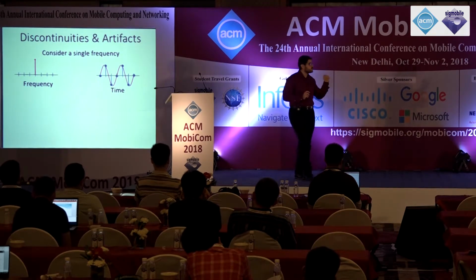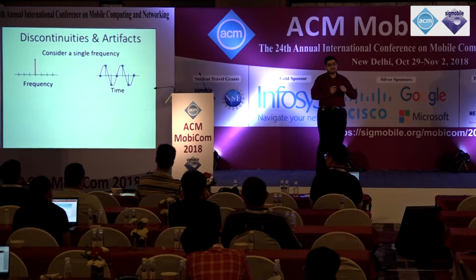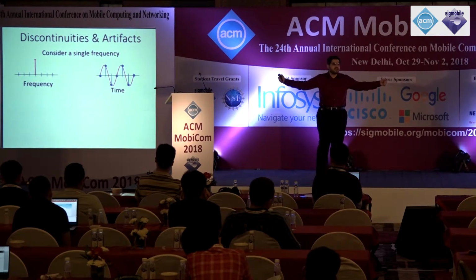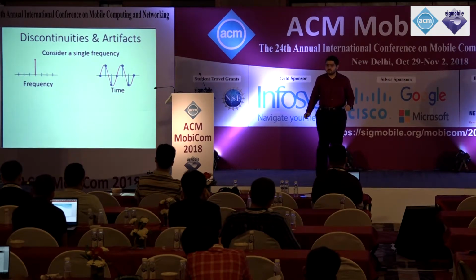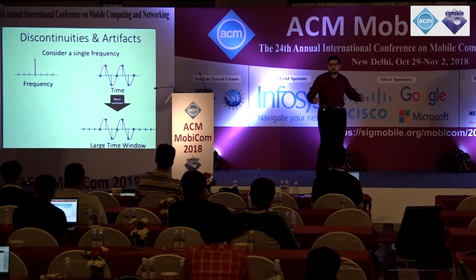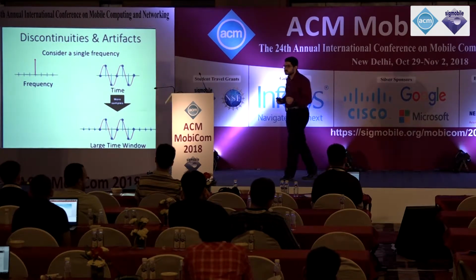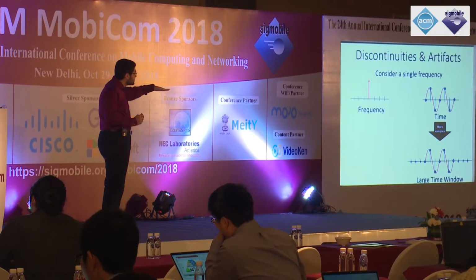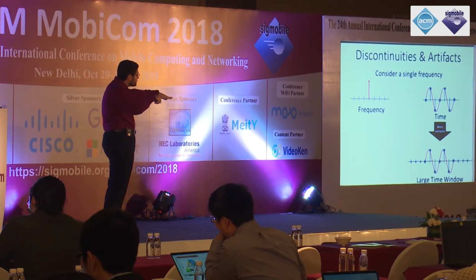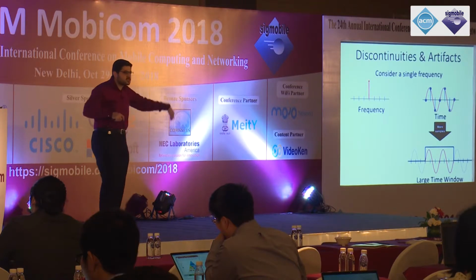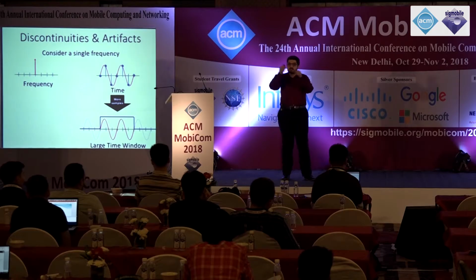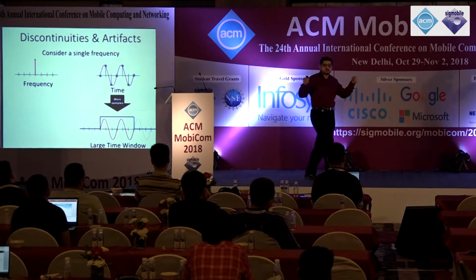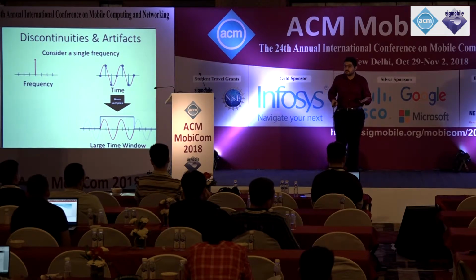Now, what did Ghostbuster do? What it did is it took an FFT over a way longer time window, something like this, way more than what we transmitted. You can think of it as a much longer sine wave that we cropped, as if we multiplied this long sine wave with a rectangle function.